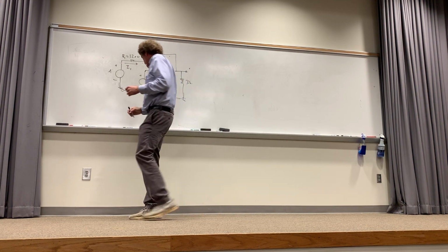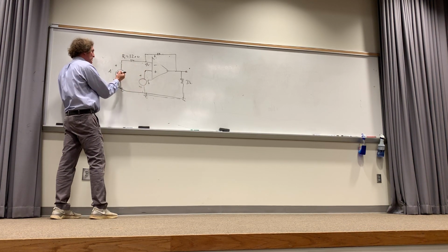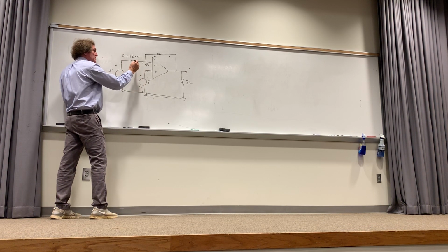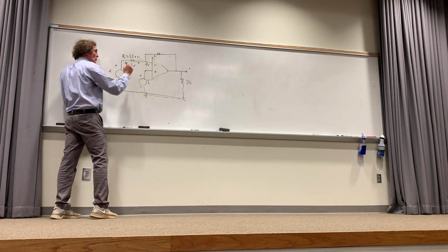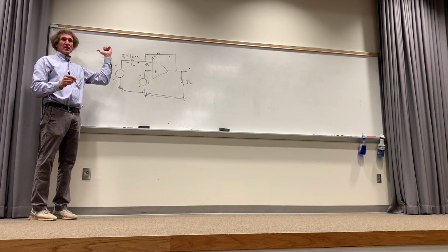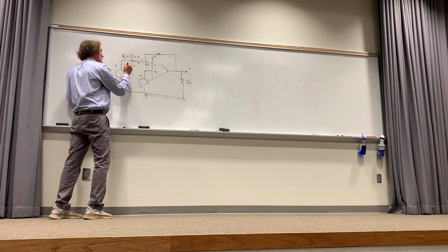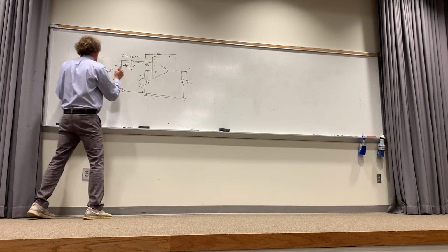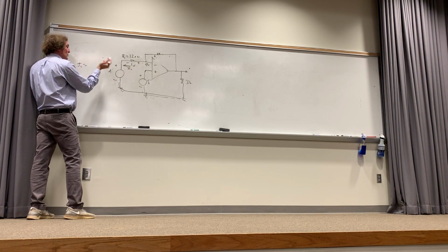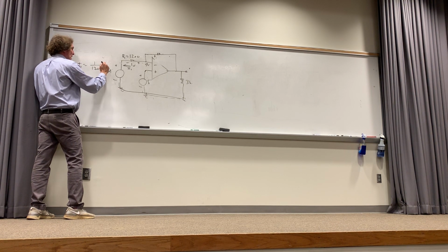Just work with me on this one, guys. So now, what do you see happening? Well, if this is 5 and this is 4, that means there's a plus to minus 1 volt difference that way. Now the current has to flow that way, correct, class? The current would flow this way, and I'll call it I1, and I1 now would be equal to the voltage difference, 1 over 1200 amps.